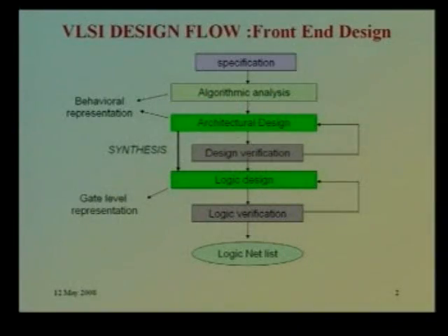When you go to synthesis, it depends on which library you require, and that is technology dependent, on whether you are going to ASIC or FPGA. So the front end is basically the same for ASIC and FPGA, but the back end is different, depending on the technology.